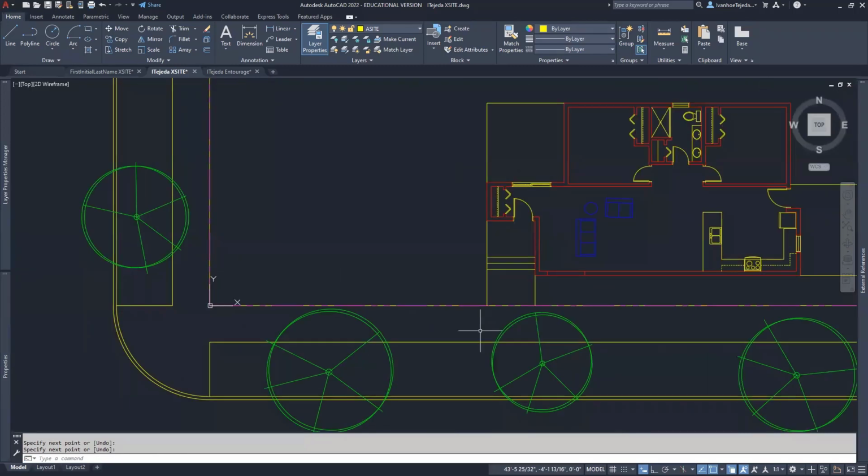I could have the sidewalk pointing here and just have my guests or myself come up along the sidewalk this way. Or I could change it so that my sidewalk is actually running the length of my house, and I would change the stairs. For example, let me just show you. If I type E, enter to erase, and I'll erase these 2 lines. All right, let's say my stairs are actually going in the other direction. So watch what I'm going to do.